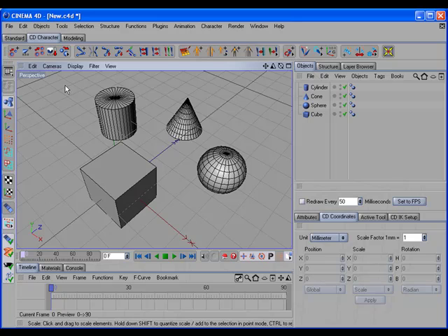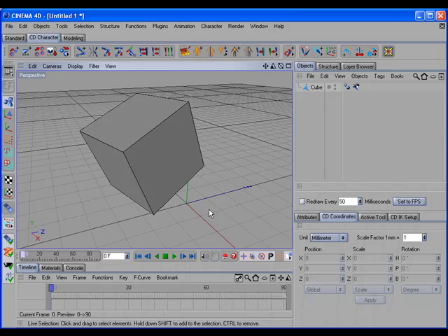Another command that I've added from CD Joints and Skin is CD Freeze Transformation. Now, this is actually a new command that will appear in the next update of CD Joints and Skin, and it will replace the CD Normalize Transform command. CD Freeze Transformation will normalize an object's matrix, but leave its geometry at its current transformation.